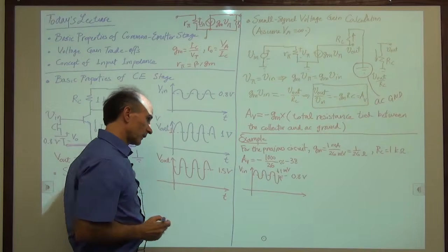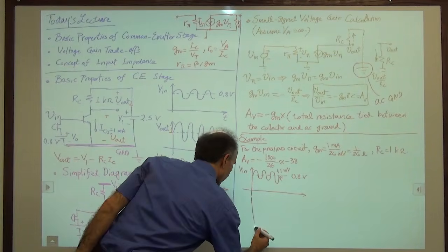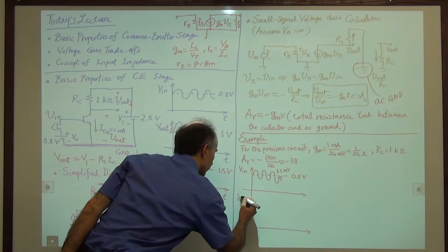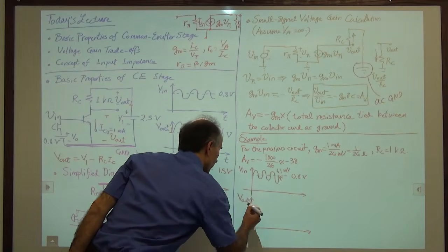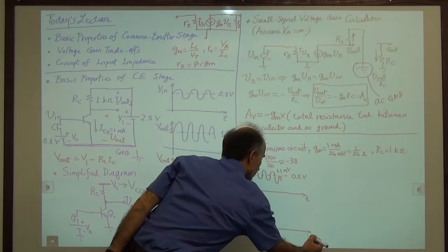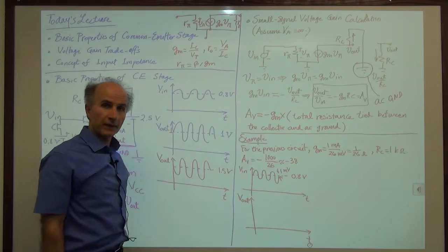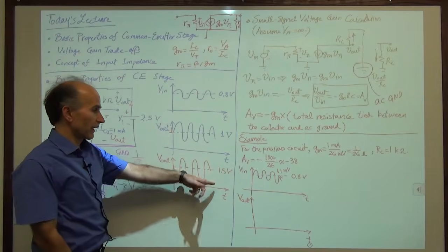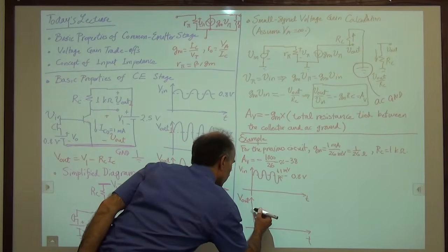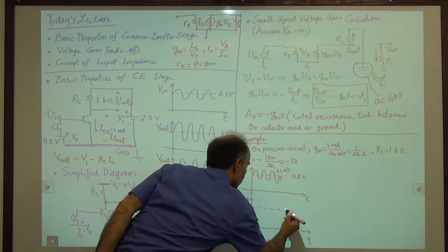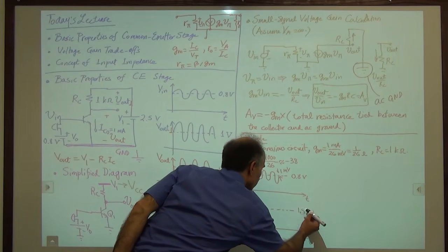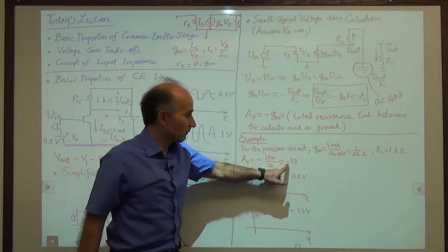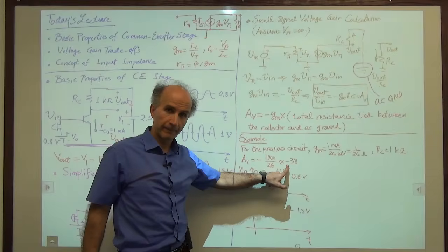All right, so this goes to the amplifier. And out comes V out. Now again, this is the entire V out. And the way we think about it is, without a signal, we just have the bias values. So remember that V out without the signal is 1.5 volts. So just keep that there. We have 1.5 volts. And then we have a gain of minus 38.